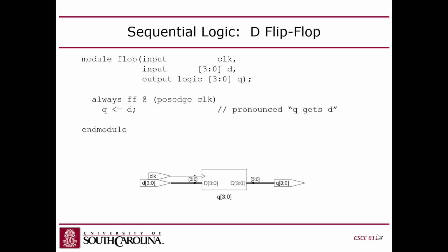And anytime you need to delay a value from one cycle to the next, like for example, if you need to carry a signal forward one cycle. So for example, we're going to be implementing branch instructions, and if you remember from 2.12, branch instructions have this notion of a control hazard. That's when you're resolving the branch, because if you're in a pipeline CPU, you'll already be fetching the next instruction after the branch while you're determining if the branch is going to be taken or not, right?